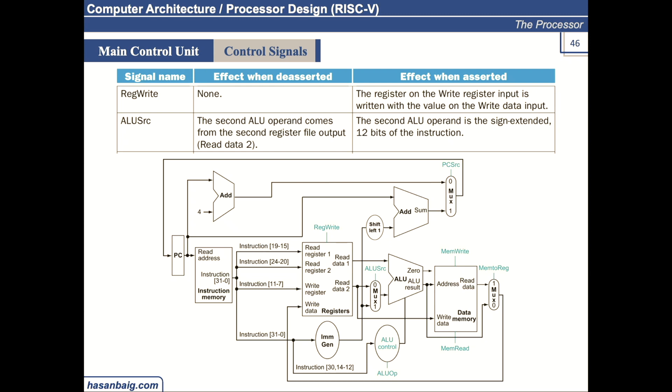If you understand this concept, then do not get confused with these zeros and ones. I can swap this out. In the exam, you might see 1 here or 0 here, or 2 or 4. Whatever value is assigned against this port means that the select signal value should be that value in order to get this data to connect to this input of the ALU. Any question?